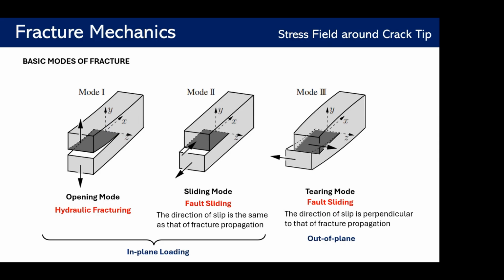If the applied force is parallel to the fracture, the second mode of fracture can develop. And the second mode is also an in plane mode. And also we have another mode, third mode, in which the applied force is parallel to the fracture, but it's the out of plane force.